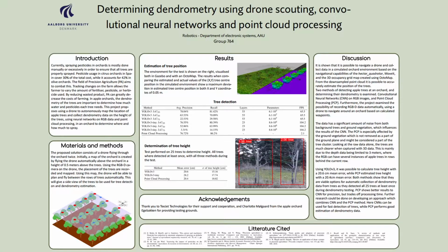Initially the drone would fly above the orchard and then, using the depth capabilities of the camera, create a map which will have the position of each of the trees. As the canopies of trees generally blend well with grass, the normal RGB images were not considered viable for this step. Using the depth data, a threshold was set to remove the ground plane from the orchard. A clustering algorithm could then be used to find the trees in an orchard.